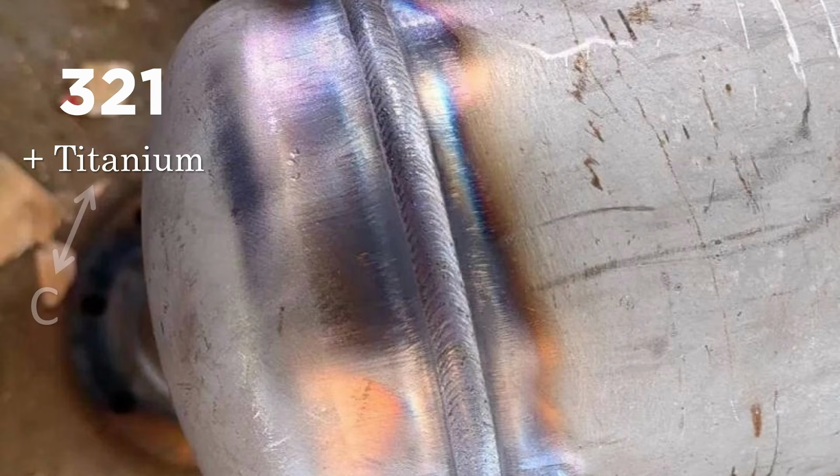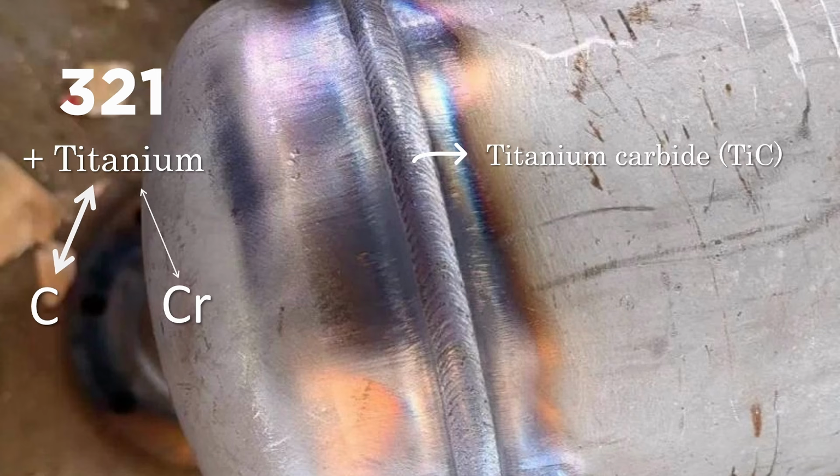Titanium has a stronger affinity for carbon than chromium. So when the metal is heated during welding or fabrication, the carbon prefers to form titanium carbide instead of chromium carbide. This means the chromium remains free in the steel and stays above the level needed to form the passive chromium oxide layer. No chromium depletion at grain boundaries. As a result, much lower risk of intergranular corrosion.